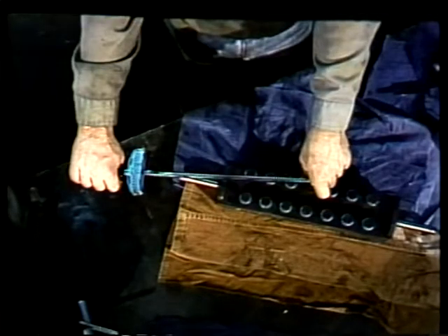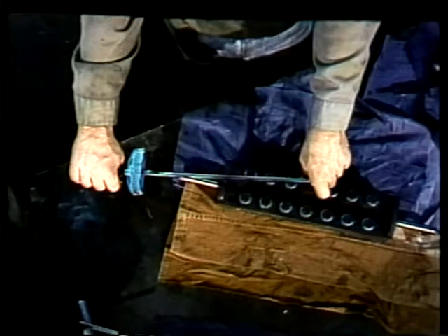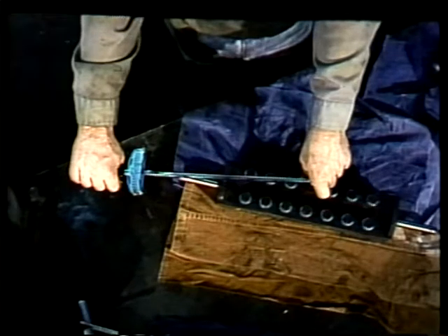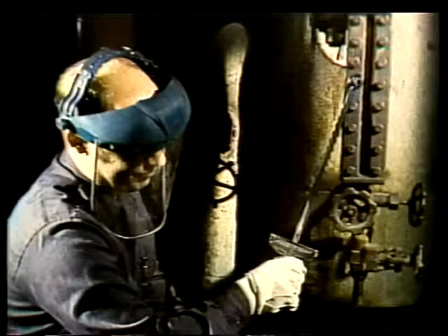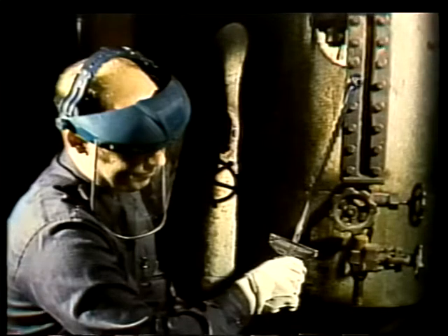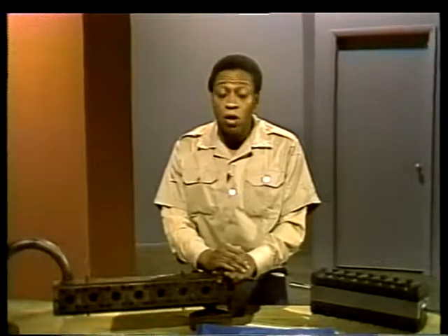Torque the bolts according to the manufacturer's instructions. Place the gauge in service and check for leaks. Then replace the illuminator. That finishes our overhaul of a flat glass gauge. Take a few minutes now to review the procedure in your text and clear up any questions with your instructor.